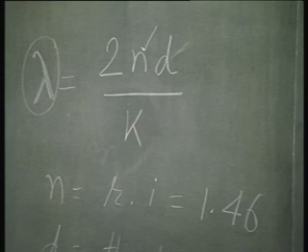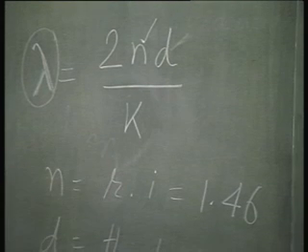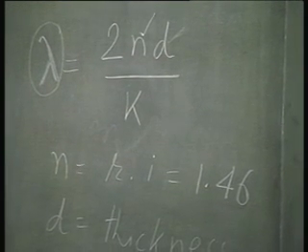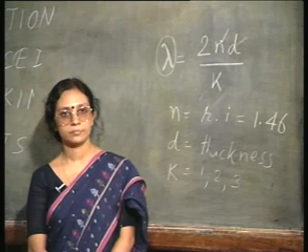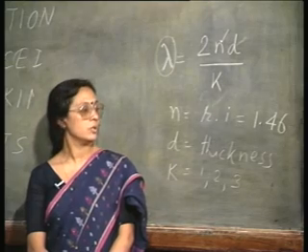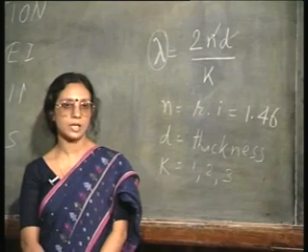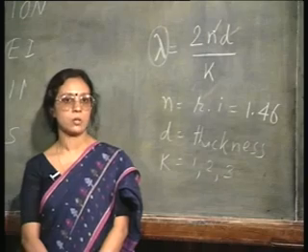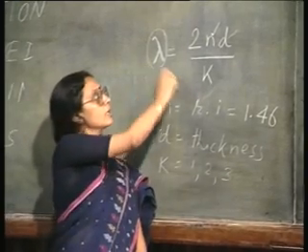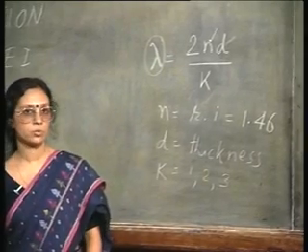one can evaluate the thickness. There is only one problem, that is, depending on the value of K, we will have a repetition in the film color. So, you may have blue colored oxide film for more than one thickness. Only one thing you need to know, that is, since you know the oxidation process time and temperature, you can estimate what is the expected oxide thickness, and then from there comparing with the color chart, one can find out what the actual thickness is going to be.